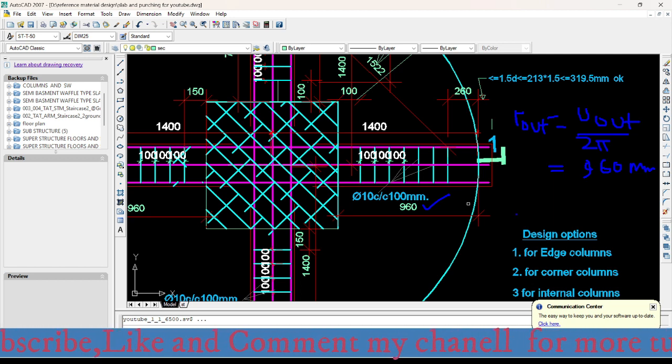So the location of the last rivet will be at 1.5d from u_out, meaning the distance between the last rivet ties and the outer effective perimeter is equal to 260. But this distance, 260 millimeter, is less than 320 millimeter, meaning 260 millimeter must be less than 1.5d, where d is the effective depth of the flat slab.